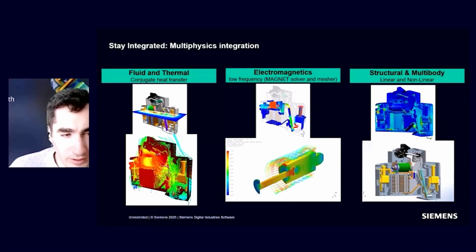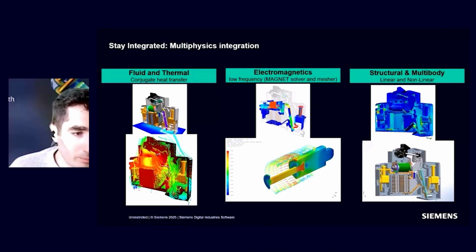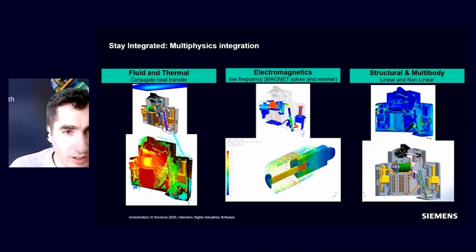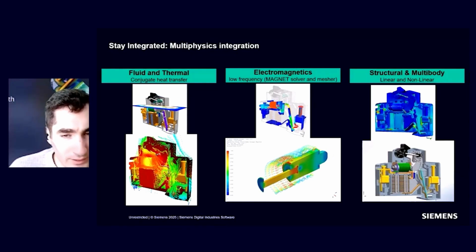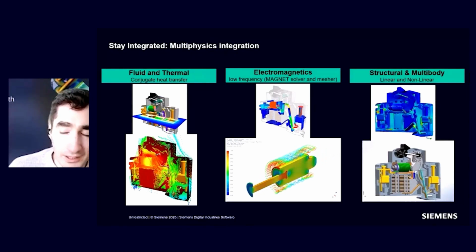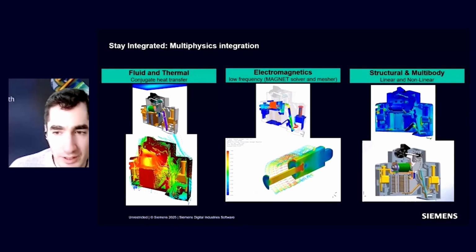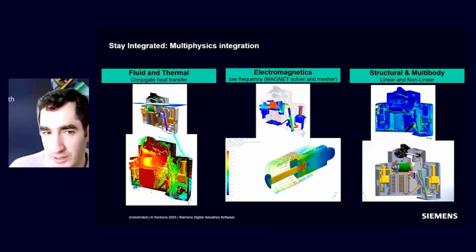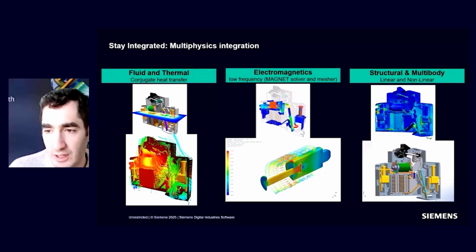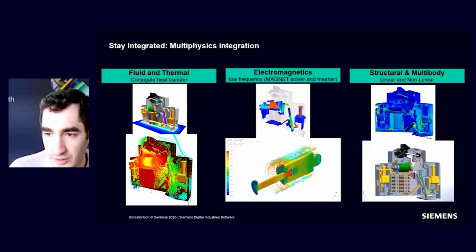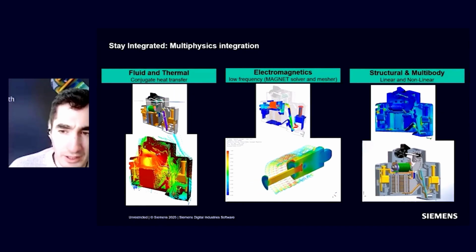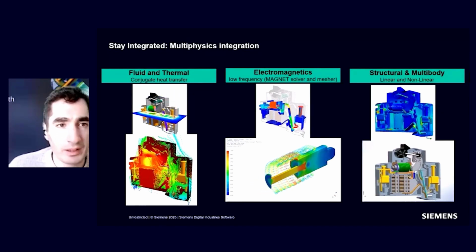So we want to ensure that all the components are not clashing with each other, that the tolerances are respected. And here the challenge is, of course, high-speed motion dynamics. These components move extremely fast, especially in short-circuit scenarios. We have milliseconds as an order of magnitude of time frame, and this requires precise calculations.